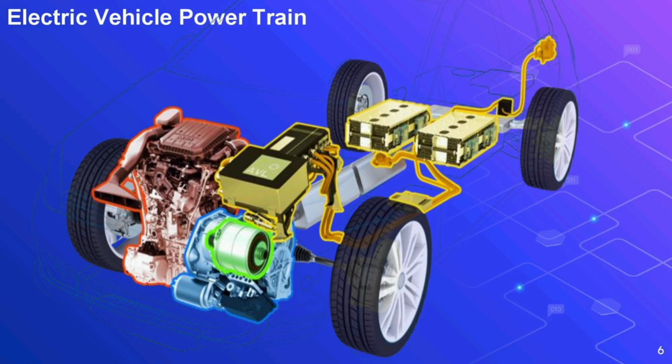It consists of an EM, a clutch, a gearbox, and the differential. The clutch enables the connection or disconnection of the power flow from the electrical machine to the wheels. The gearbox consists of a set of gears with different gear ratios. The advantage of this configuration is that the weight of the transmission is reduced. The electric vehicle drivetrain alternatives based on the power source configuration.